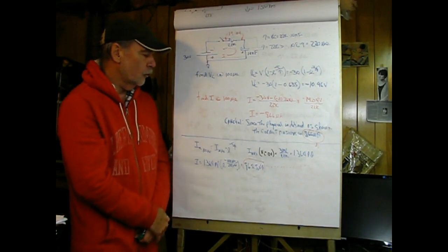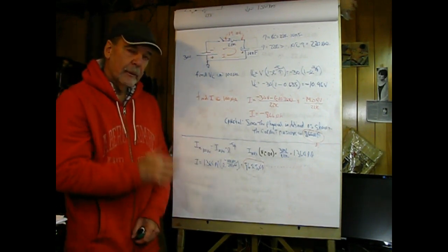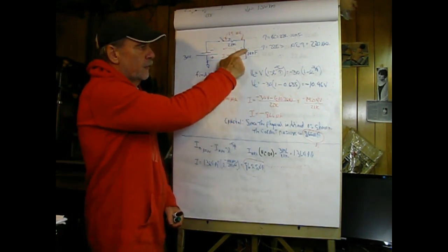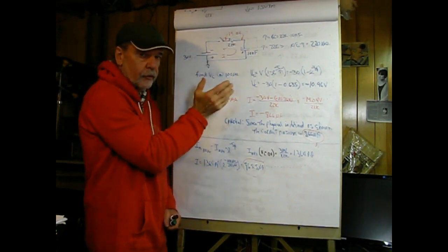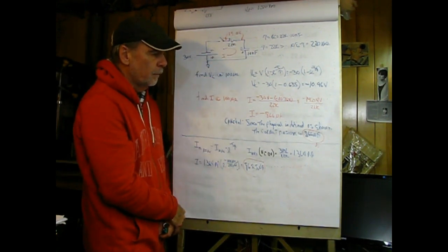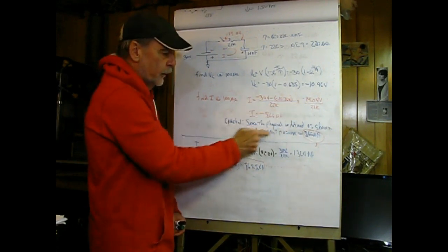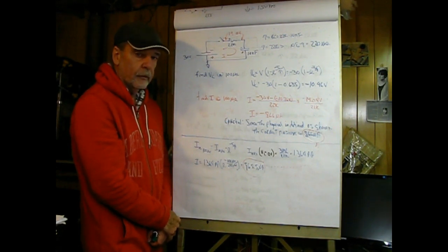Now find I at 100 microseconds, and this is where you have to be a little bit careful, because what we would do would be subtract the capacitor voltage from the source voltage. That would be the voltage across the resistor, and then just use Ohm's law. And doing this with polarities, we end up with a negative current of 866 microamperes.